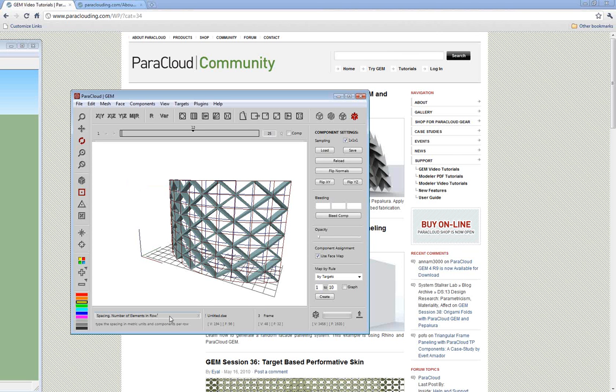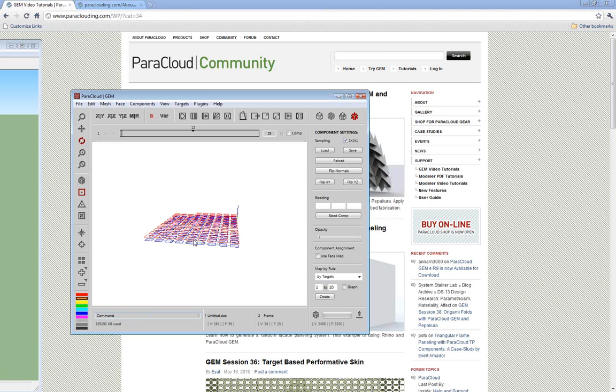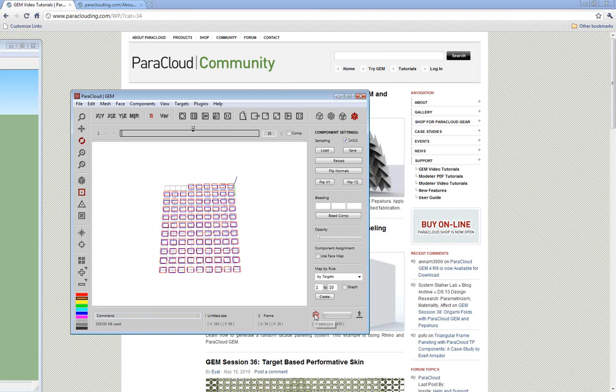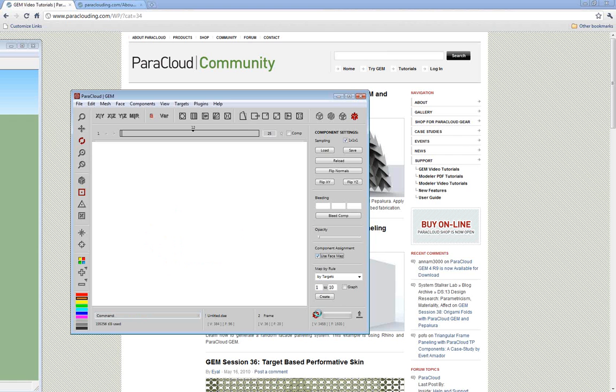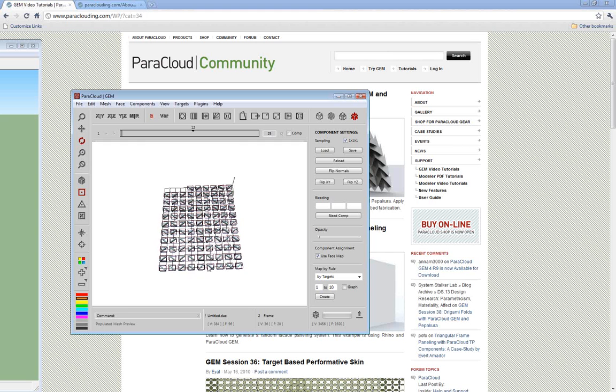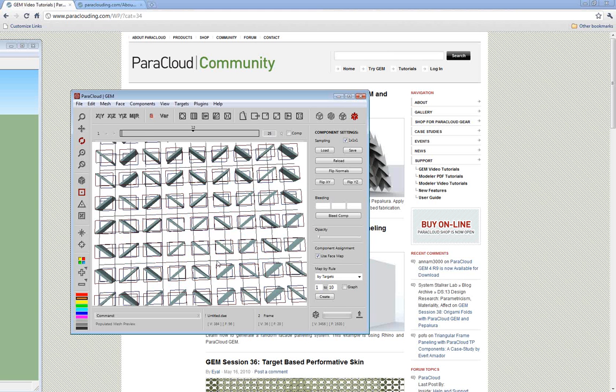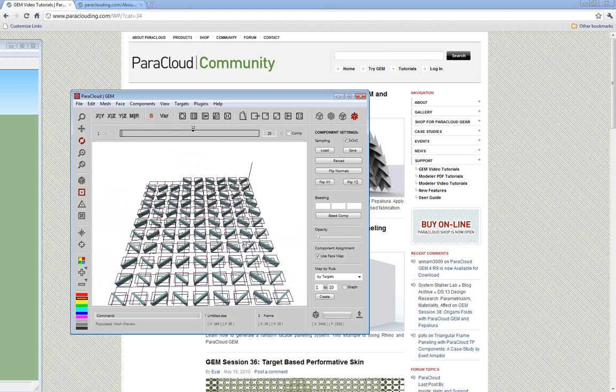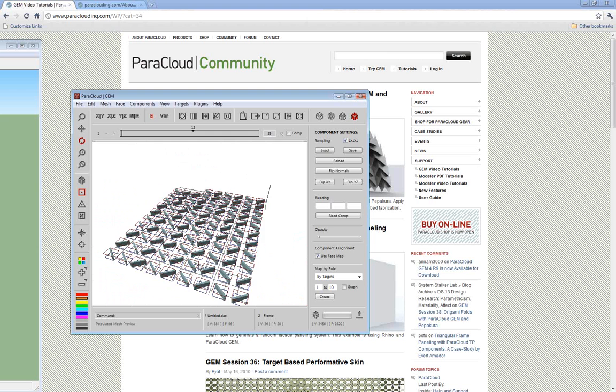For example, I use 0.6 maybe here, and I'm generating an unfolded view of my components, which will allow me to get those ready for generating a quick 3D print and then assemble those. We have assembly markers that we prepare with those as well in the DXF output.